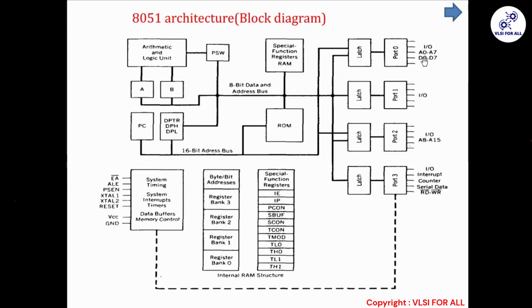Similarly, let it be external data memory I am configuring, and from that, I have to fetch the data as well as write the data. I can configure my port 0 as data D0 to D7 pins for accessing that data. So these 3 important things it is doing.